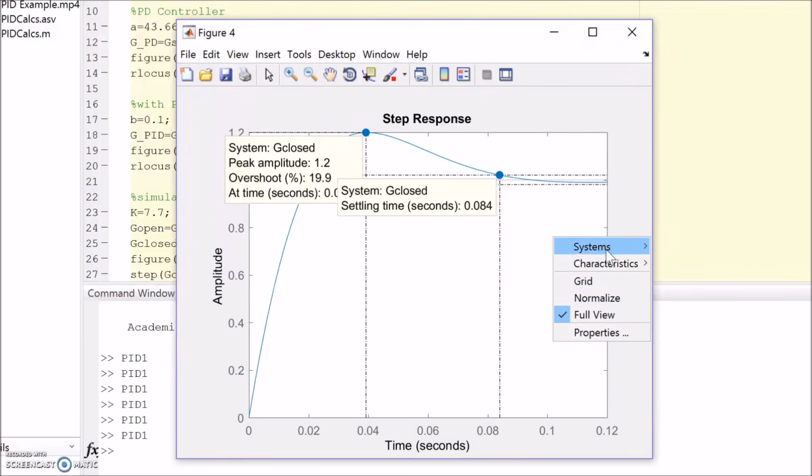We also had that criteria about steady state error, but we said that as long as we designed our PID controller, we should end up with 0 steady state error. So we can see here that I put in a unit step, so that means that we would expect that the response should be 1, and we can see that we've definitely got this final value of 1. So that would suggest again that we've achieved that steady state error requirement.